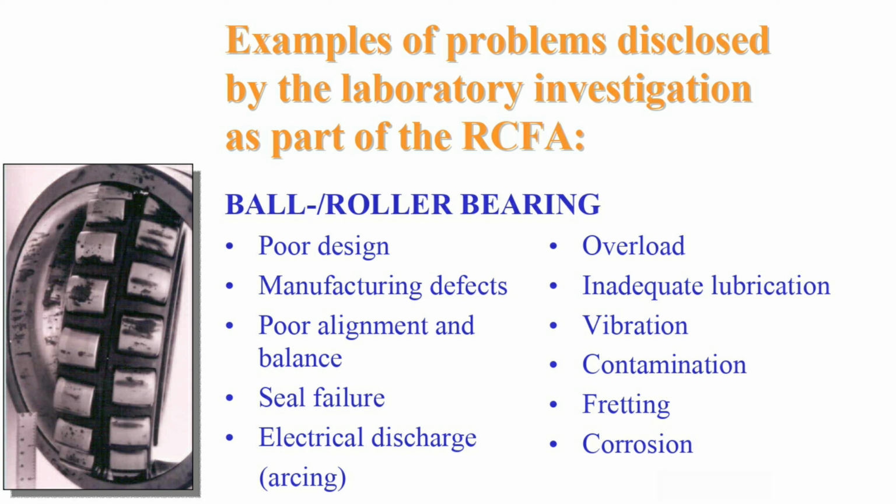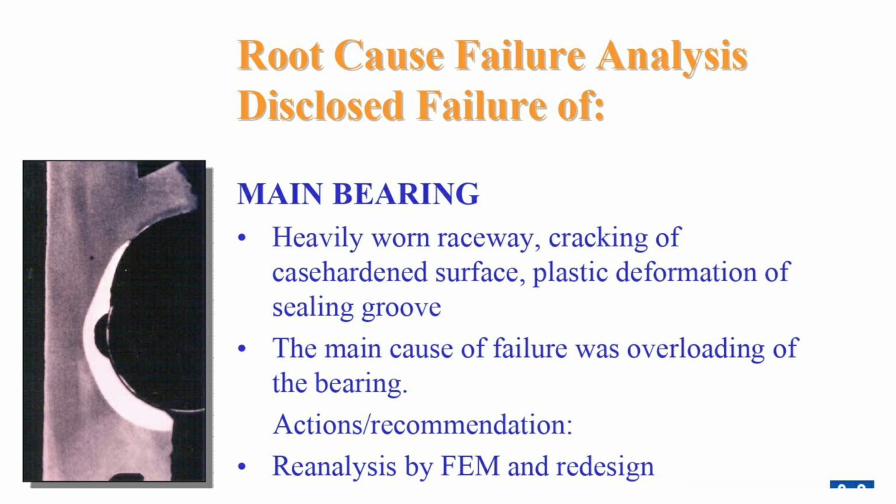Root cause failure analysis disclosed failure of main bearing, heavily worn raceway, cracking of case-hardened surface, plastic deformation of sealing groove. The main cause of failure was overloading of the bearing. Actions and recommendation: reanalysis by FEM and redesign.